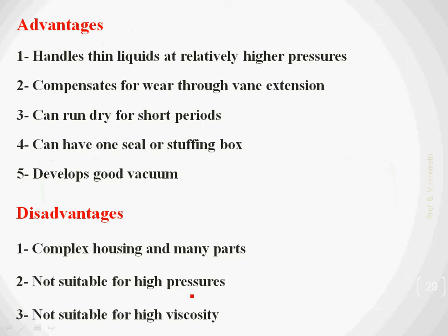And the advantage of using such pumps is it handles thin liquid at relatively higher pressure, and it compensates for wear through the vane extension, and it can run dry for a shorter period of time, which is not possible in the case of gear pumps, and it can have one seal or stuffing box. It also develops a good amount of vacuum. So those are some of the advantages, and similarly the disadvantages are the complex housing and too many parts in the case of vane pumps. It is not suitable for higher pressure as well as high viscosity fluids.